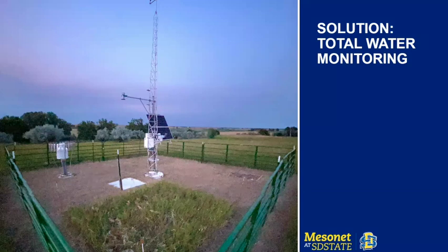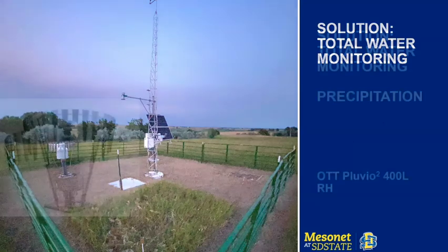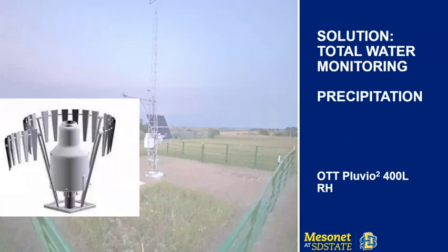This is an example of one of the stations. You can see the natural cover plot in the foreground there. Each of them has a weighing precipitation gauge, because traditionally most Mesonets measure rainfall only with a tipping bucket rain gauge. Because getting high rain rates is important, and also collecting snow is important, we use weighing gauges. They're all shielded, and most of them have heated rims as well.